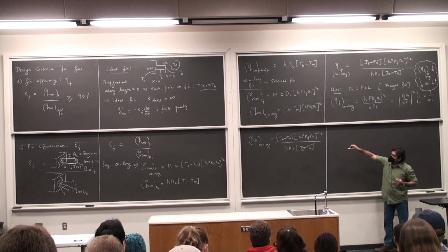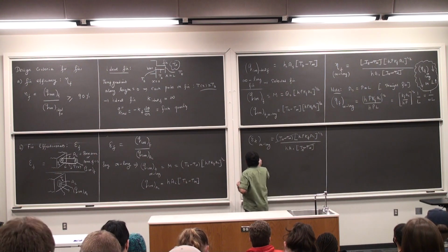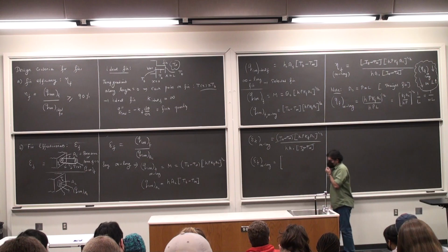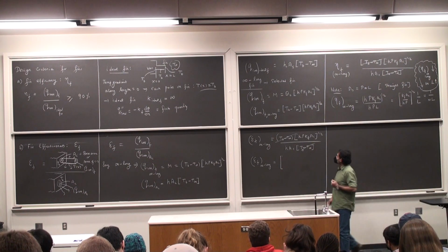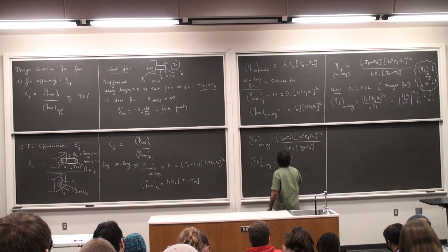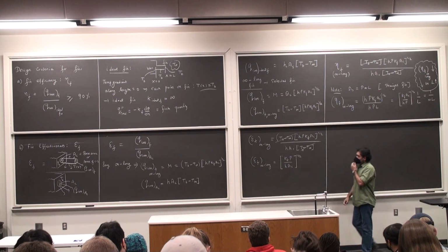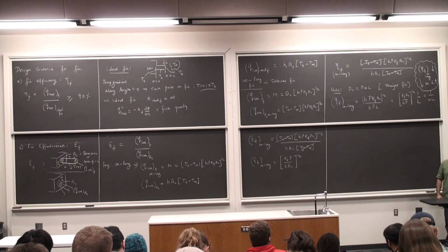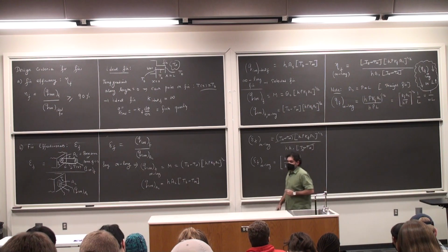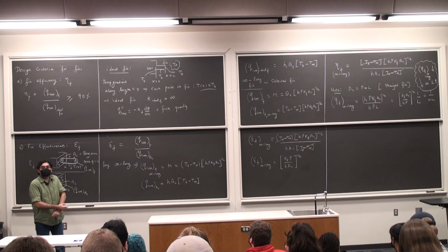Now I'm going to take these parameters. I have h in the numerator to the power half, h in the denominator, AC to the power half, AC in the denominator. So epsilon f is going to end up being this combination of parameters: kf, then perimeter, and then h AC to the power 1 by 2. This is not little m. We just looked at what was little m there. So this is some other weird combination. I'm not interested in giving it a name, but I'm interested in looking at the parameters that influence the effectiveness.